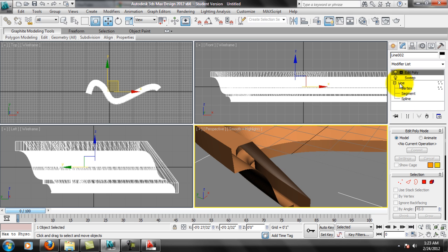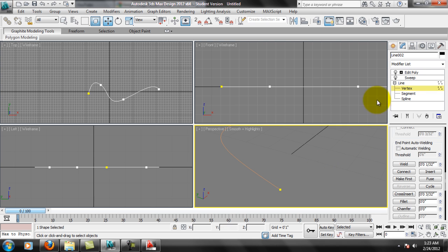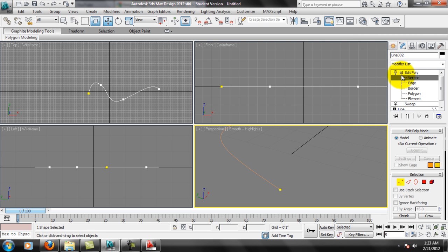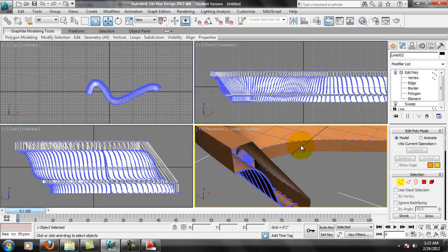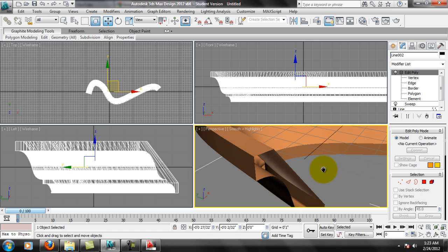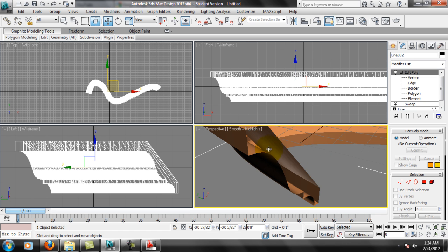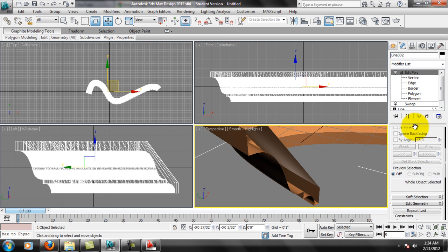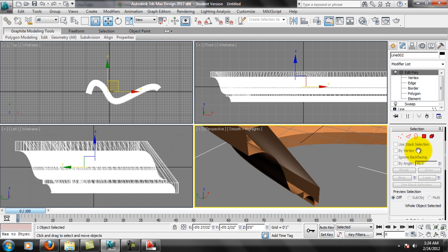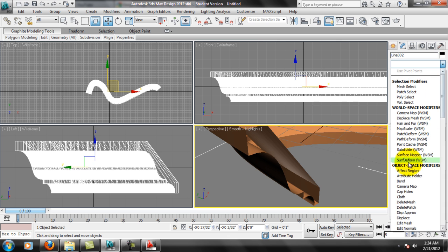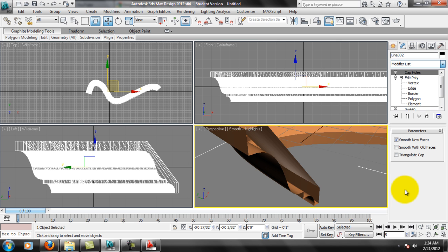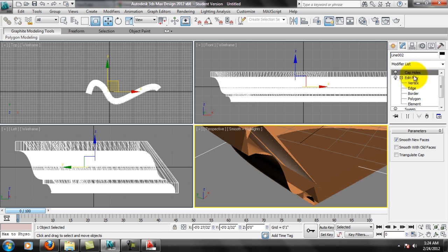Let's see my vertices here, select vertex. Oops, not on the line, I'm sorry, up here under edit poly. So we've got a lot of vertices going on here. And again, that's just simply because of the way that I created the profile. It would be best if you use arcs in the future here. It might save some of these problems. See if the cap holes will exit now. No.